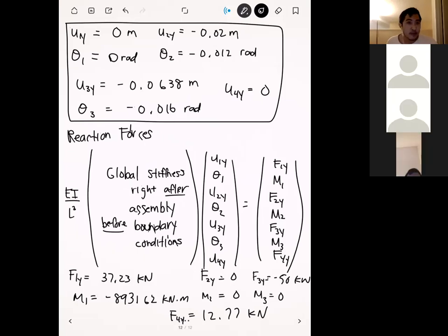So the displacement solution that we got had all negative values, right? So theta was negative, is it counterclockwise, or actually clockwise, correct? Right. The standard that I use is counterclockwise is positive radians and clockwise is negative radians. So that means the spring isn't strong enough for that load, right?